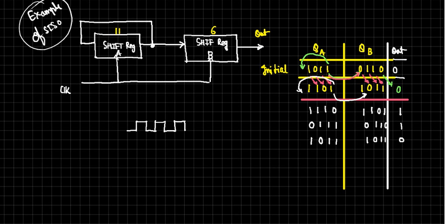I need to simply transfer that, and also I want to make a copy of those boys and girls who were present. I want the initial state also. What happens whenever the clock signal comes? This boy will go here, because it is a shift register and I connected it so that it will simply get the input from the first one. That's how we have seen in the previous circuit. Just because it's a 3-bit or 4-bit register, it can save only 4 bits. The last bit which was there will be transferred as output.